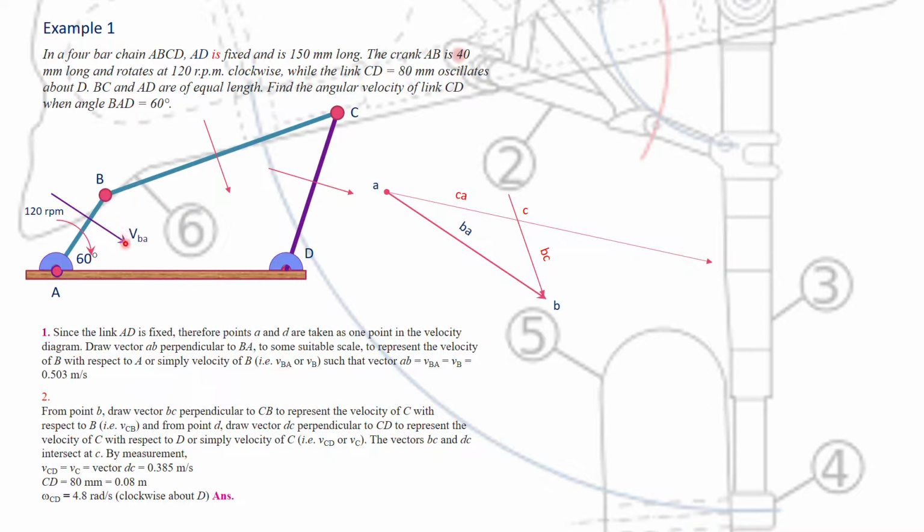So I have got this velocity here just now. But remember, for the velocity diagram, you have to use another scale of 1 cm equivalent to how many meter per second. Just now you used a scale for the space diagram, 1 cm is equal to how many mm. Now you have to use another scale to draw the next diagram, 1 cm is equivalent to how many meter per second. So once you have got the scale, you get the length of this VBA in cm.